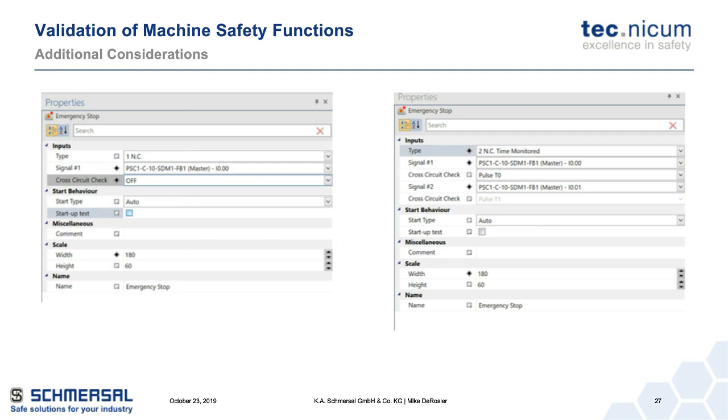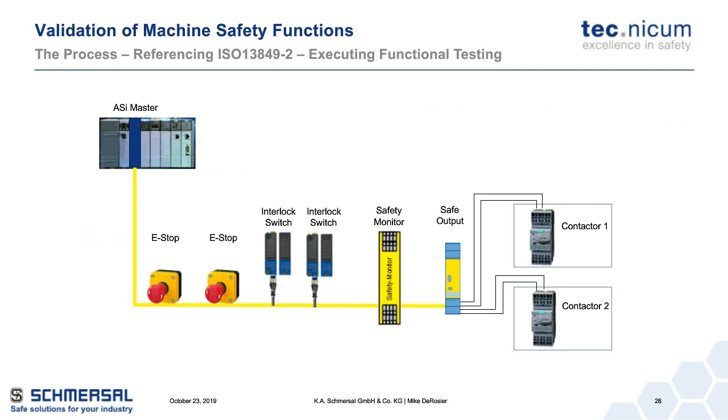In another case, what we found was that the e-stops are all dual channel. It all went back to a programmable safety controller. The programmer had not coded it properly, and only half the e-stop circuitry was working because of the way the function block was configured. Well, now we start getting a little bit more complex because we have safety over a network.